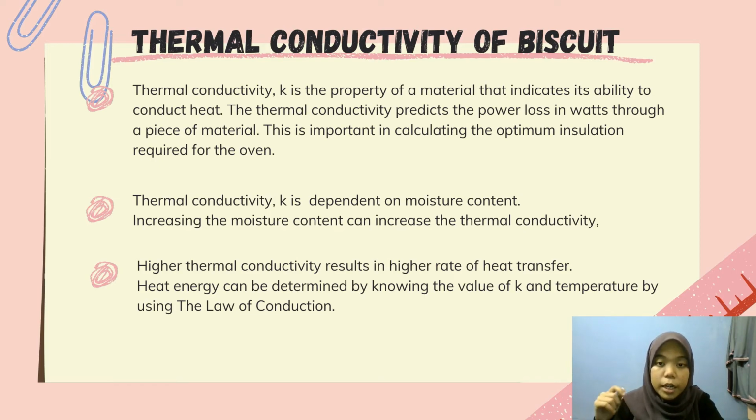However, on the other hand, the thermal conductivity of whole biscuit is less affected by the moisture because it ranges from 0.20 to 0.23 watt per meter Kelvin. This is because for the whole biscuit, the effect of the fat is so heavy that it hides the effect of moisture.